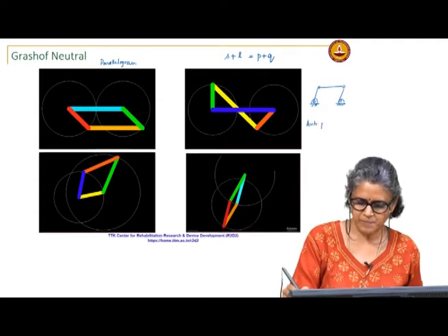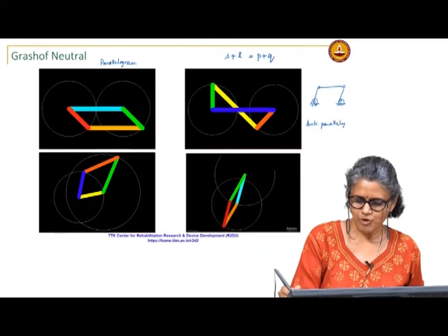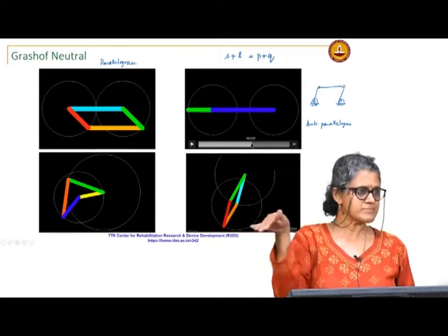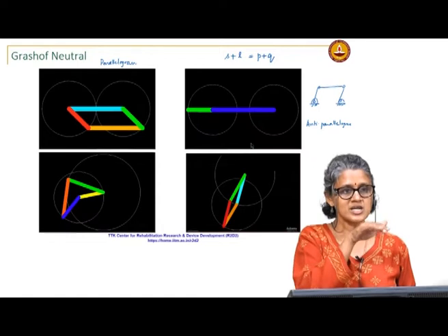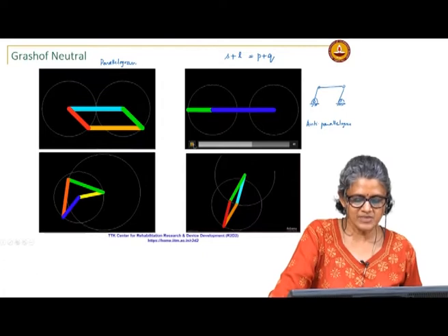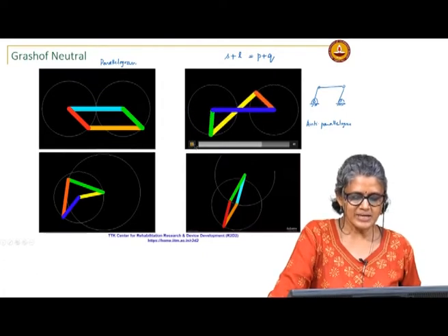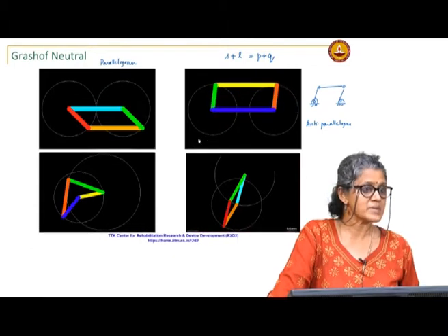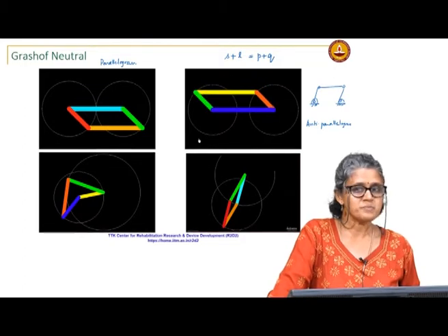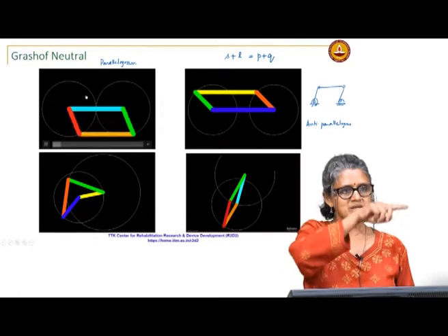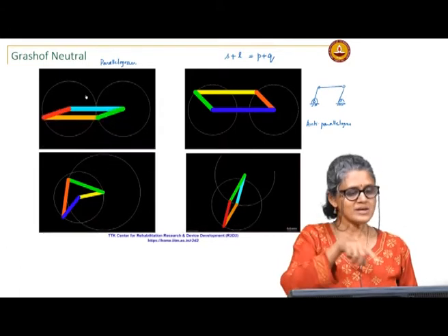So, it is the same links in the anti-parallelogram form. You can see here, when the links line up like that, that is called a change point, and there is some unpredictability associated with that change point. You started off with an anti-parallelogram mechanism, and you can see here it switched to a parallelogram mechanism. So, your output becomes unpredictable. In this case we did not see this because of the inertia of the links; if the inertia of the links is able to carry it through, then you do not have a problem.